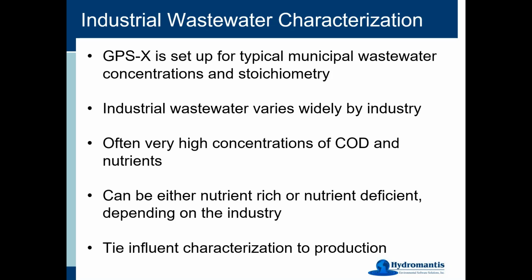I've worked on a couple of food processing places where the wastewater that was generated and sent out for treatment was very dependent on what it was they were making. Their fish stick production produced a certain kind of waste that was very different than when they were making French fries and other things. So these are all very interesting aspects of industrial wastewater that it varies quite a bit. Often they're very high concentrations. We did a project a few years ago with winery waste that was over 250,000 milligrams per liter of COD.